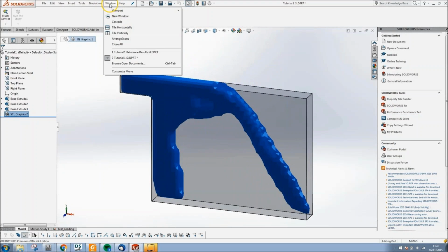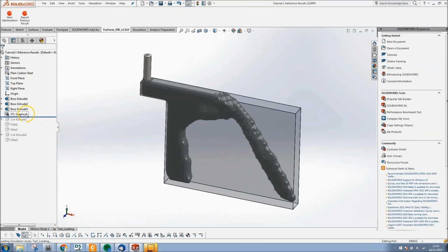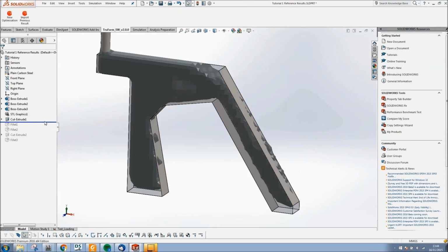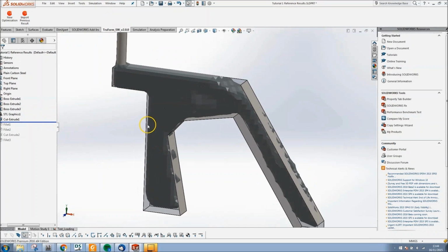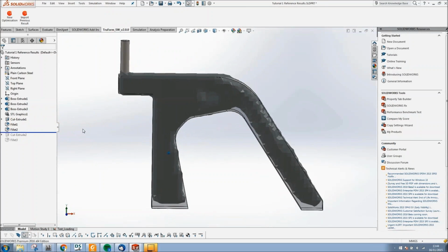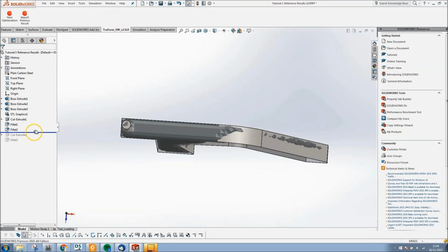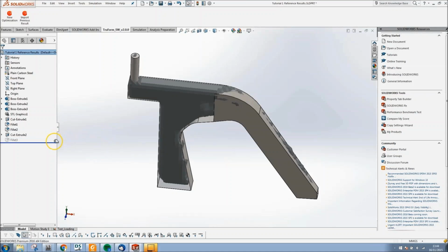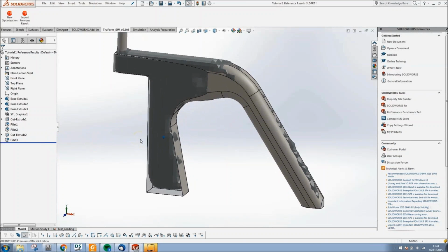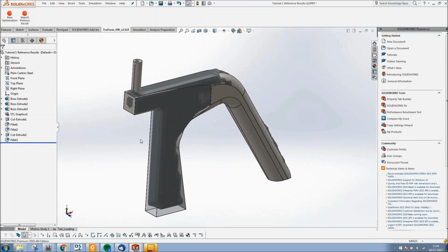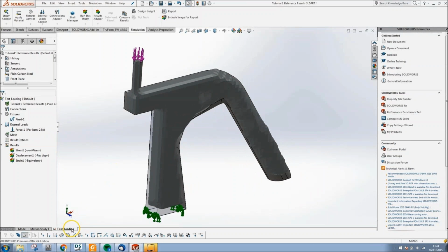So what we'll do next is we'll just use some reference results here to roll forward through our design tree. So first of all, we'll cut out the material that's unwanted, and then add some fillets. And then with an extra sketch, just trim and taper that rear leg, as TruForm is suggesting, and then finally add a nice smooth fillet to complete the shape. So you can see very quickly we can develop around the part to achieve what we want as a design.